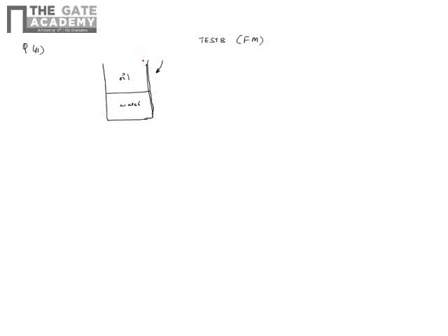So assuming that here you have atmosphere and you have atmosphere on the right side also, the force due to the atmospheric pressure will cancel out. So we need to just take the gauge pressure, because even if you start with atmospheric pressure here and go on adding the pressure, on the right hand side you have only the atmospheric pressure. So basically atmospheric pressure is not taken in hydrostatic calculations, only the gauge pressure is taken. That's what I want to convey.